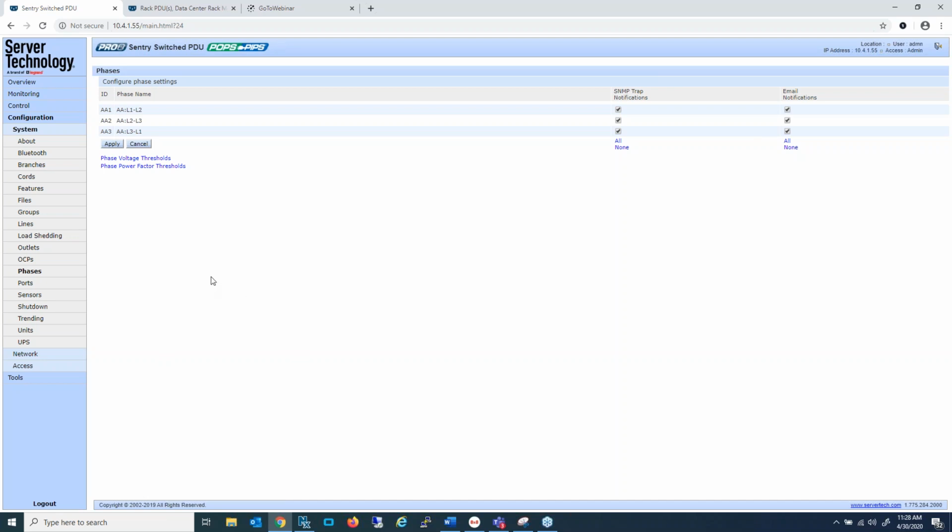Right. Okay. Well, there are two ways to approach that. Ideally, you'd be looking to identify the individual loads of everything plugged into individual outlets, using the per outlet power sensing feature. If your PDU contains per outlet power sensing, you can review the current for each and every device related to which phase it's plugged into, and you can see if it's possible to move power cords around to balance out the phases to have a more balanced system.